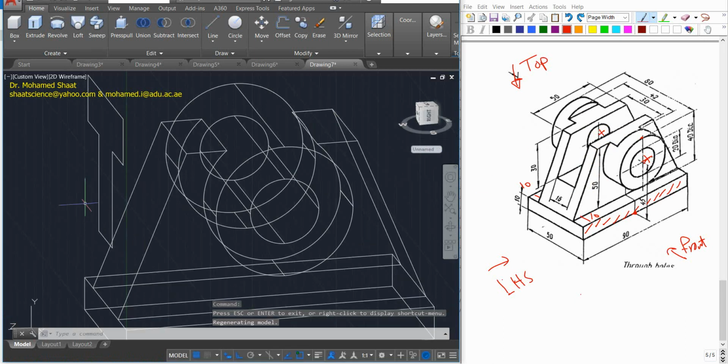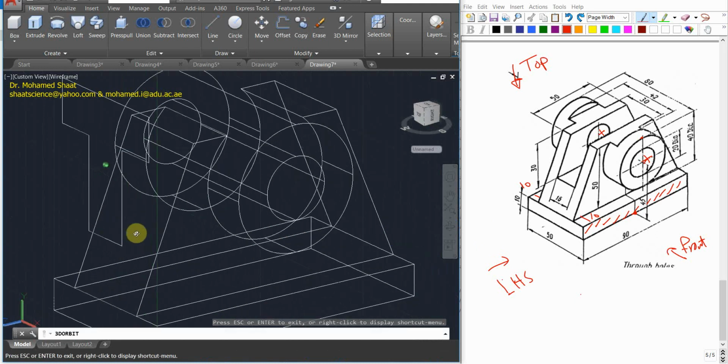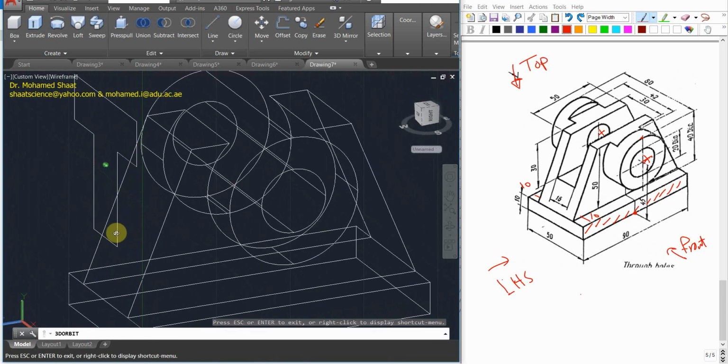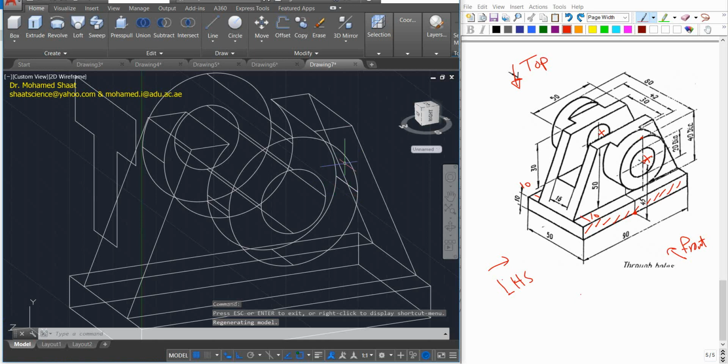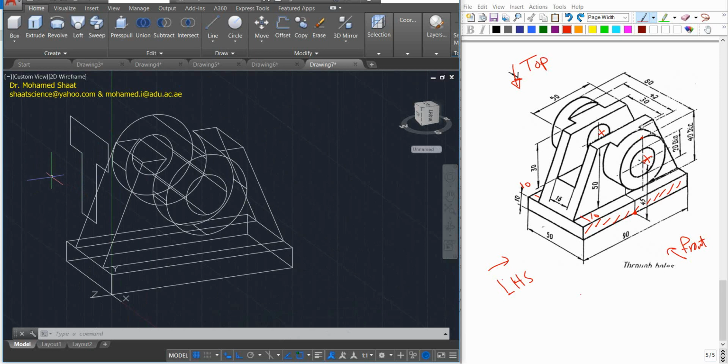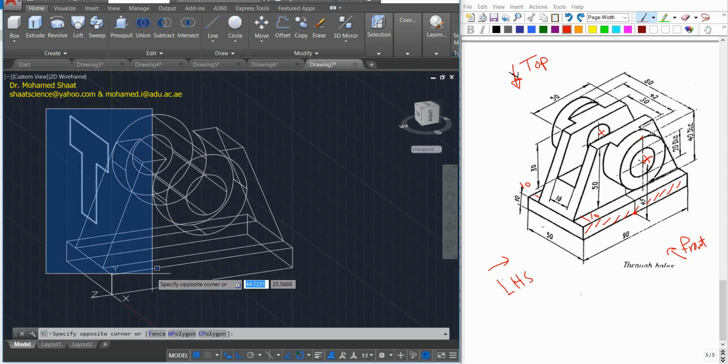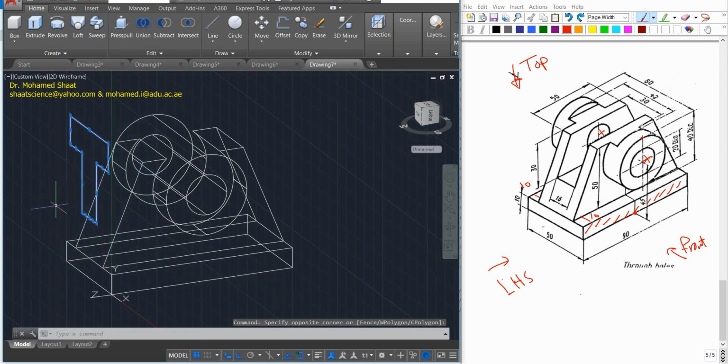It would be challenging for some of you to get the idea of this T-shape, but again, this requires more practice. As you practice more and deal with more complicated shapes, increasing the level of complexity, you're going to be in good shape. This is what I mean by practicing. You have to practice more and think how you can create these objects using AutoCAD. As you practice more, you'll become more expert. So you choose this shape, join and press enter, so it becomes a single object.